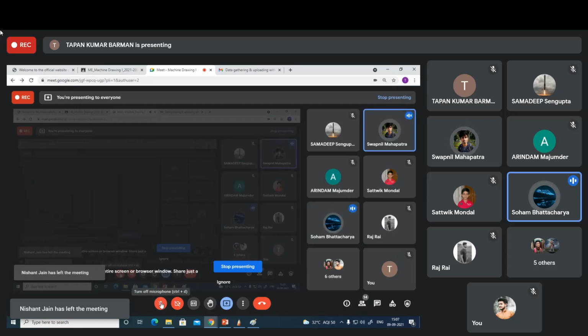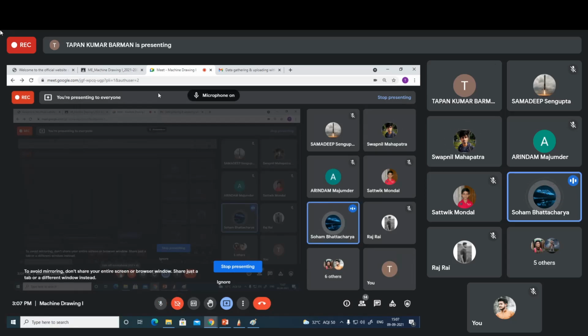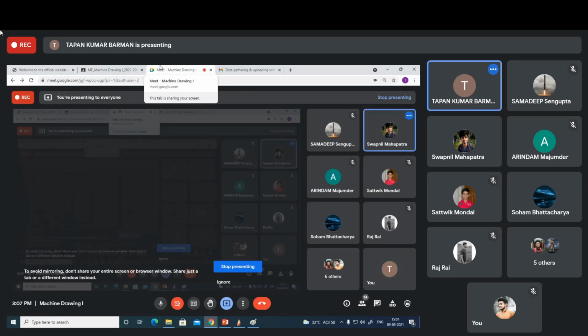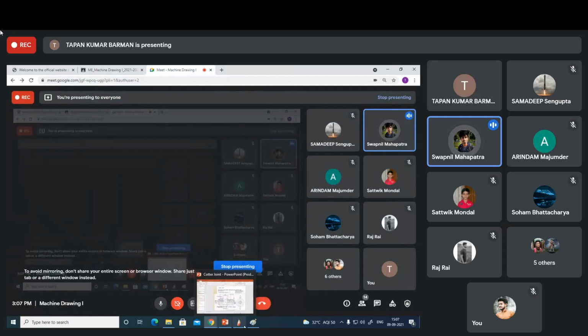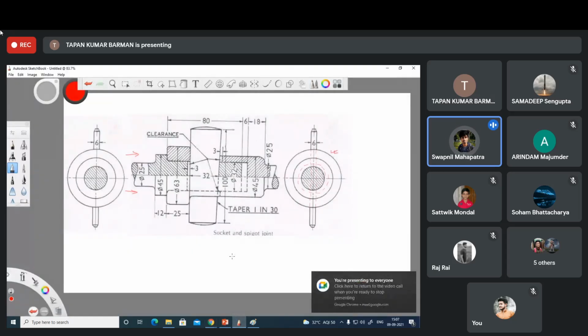If you are taking the first angle view, then sorry, the left hand side view has to be on the left hand side. Yes. Now tell me. Sir, actually the main convention is that it is a 3D object, and now we are projecting the vertical projection, the horizontal projection, and the left hand side projection. Now if we are rotating the plane in anti-clockwise, then it will always be on the right hand side or the left hand side. I mean, it cannot change.